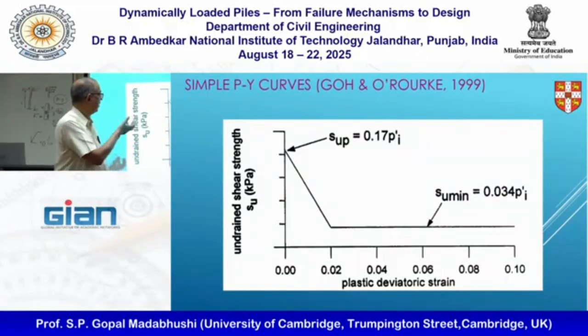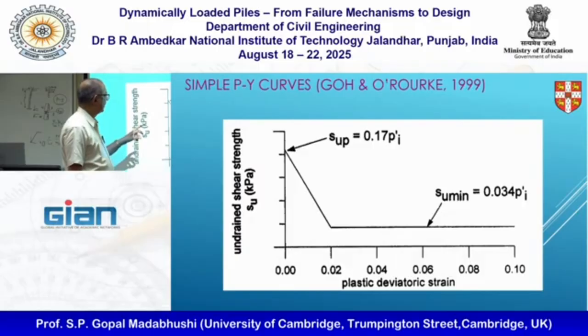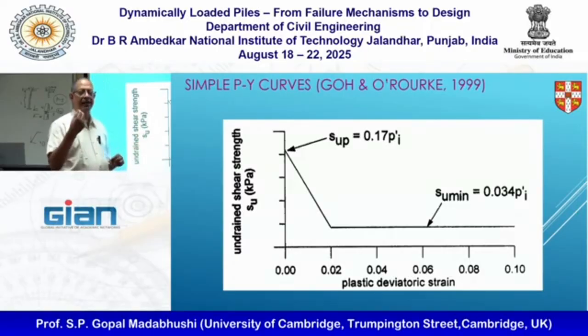Clay will have an undrained shear strength, which we all know or can work out. A simple UCS test should tell us that. But what happens when you subject the clay to cycles? It will soften. If you apply an earthquake loading to a nice clay bed, it will soften with cycles.